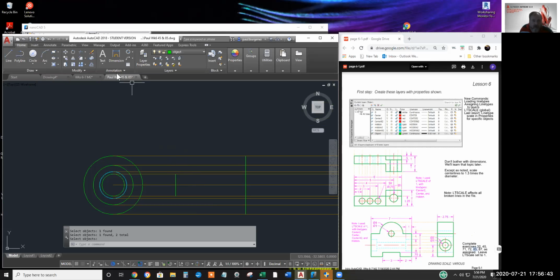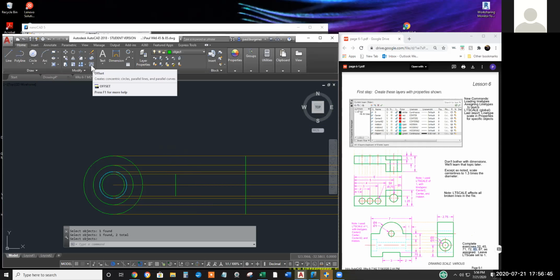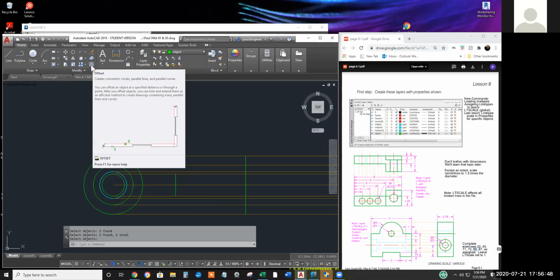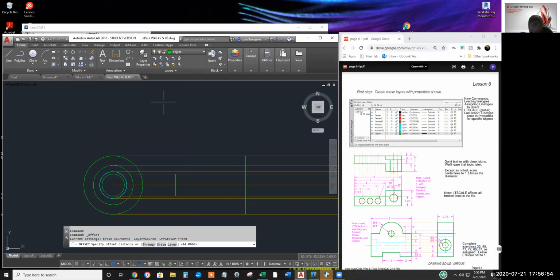Where was I? You were gonna say that dimensioning to hidden lines is forbidden. You forgot the end of that sentence. There you go. Unfortunately, I can't think of a way to avoid dimensioning the hidden. You've got to do a breakout view. You've got to cut that thing. Yeah, section. Yep. We'll get into section views first day of intermediate.